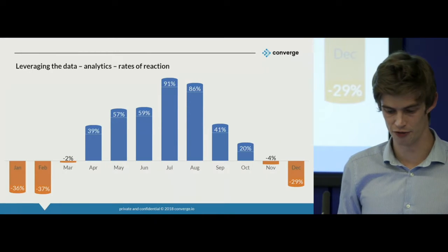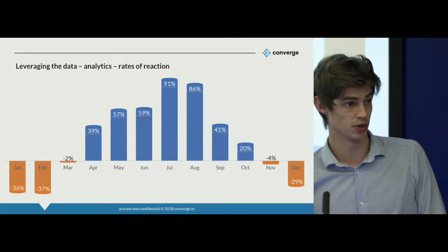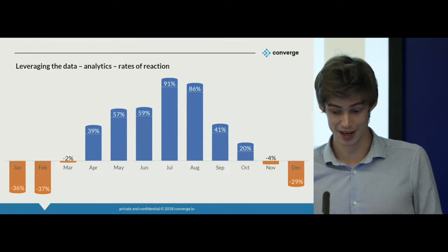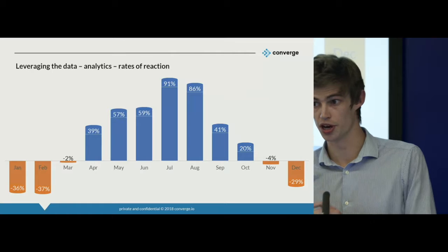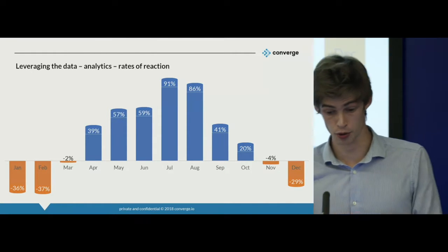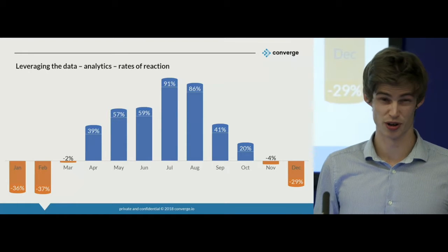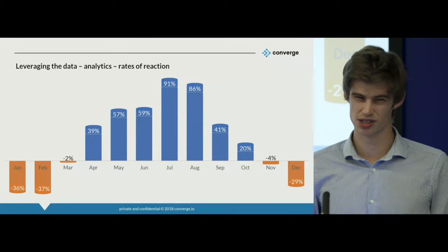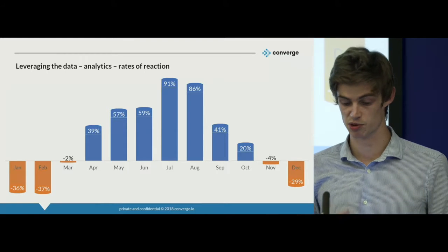But using this we can now infer exactly how fast the concrete cures. So we know in the depths of winter that concrete is actually curing a third slower than those cubes are going to give us credit for a few months of the year. And all the way through to the depths of summer where we can actually find our concrete's curing twice as quickly.